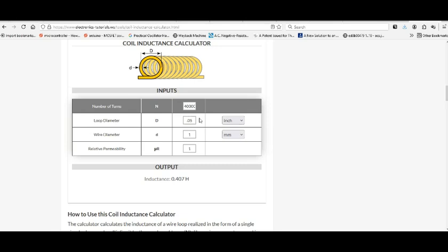Now, one thing is I diddled around with this. I actually took some 26 gauge and wrapped it around 18 gauge wire. It didn't give what Harold Wheeler, with his equations, was saying it would give. And if you go in depth on Wheeler's equations, they mention that the equations fall down in certain instances, like where the length is much greater than the width. So the further you get away from that, I basically wound wire around like 5 feet of other wire, and it stunk.